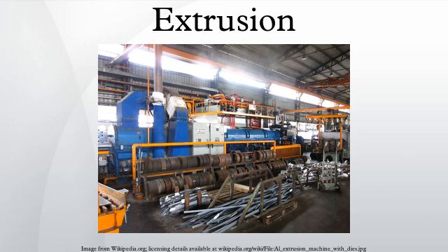Indirect extrusion. In indirect extrusion, also known as backwards extrusion, the billet and container move together while the die is stationary. The die is held in place by a stem, which has to be longer than the container length. The maximum length of the extrusion is ultimately dictated by the column strength of the stem. Because the billet moves with the container, the frictional forces are eliminated. This leads to the following advantages: a 25 to 30% reduction of friction, which allows for extruding larger billets, increasing speed, and an increased ability to extrude smaller cross-sections.